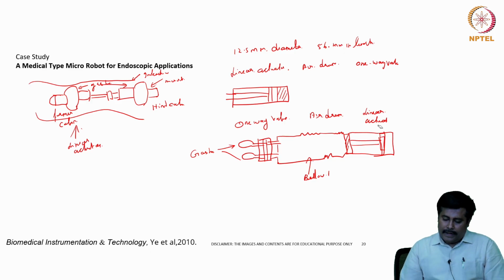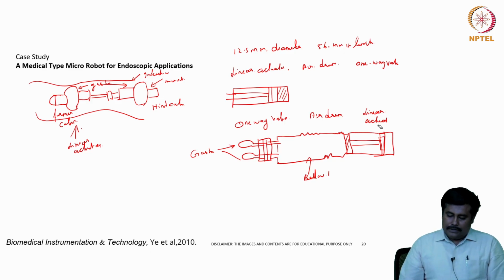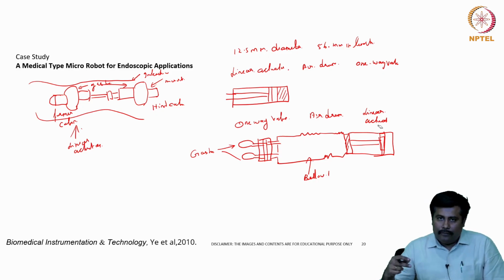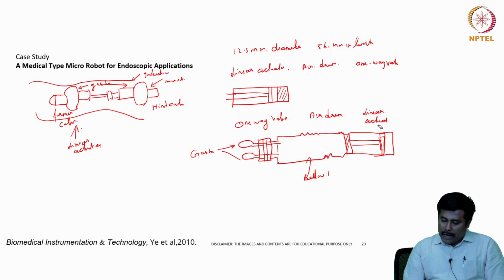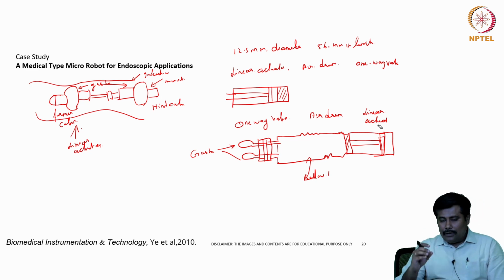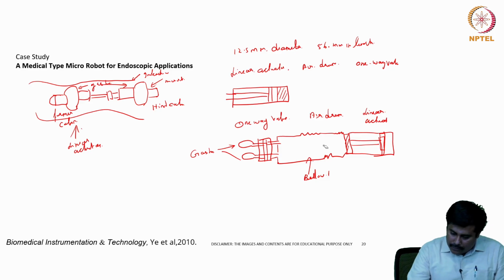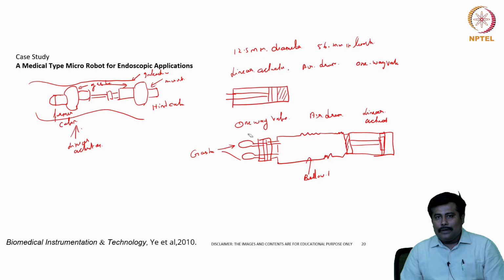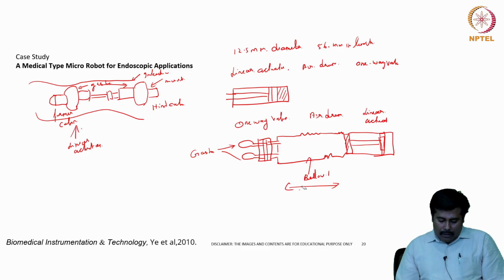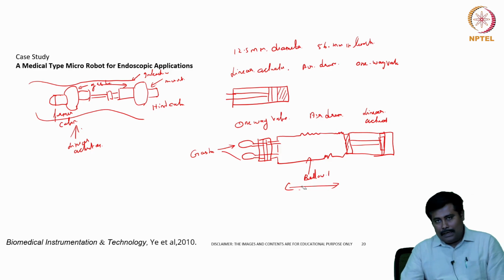So, this is a kind of linear actuator. What happens is the overall arrangement, if you see, the linear actuator is meant for giving a kind of motion to the air drum, and this air drum will give a kind of inchworm mechanism. The overall locomotion happens through this air drum, so we are trying to actuate this gas bag. When these gas bags get actuated, appropriately we can have a kind of peristaltic motion in this particular air drum, and then the overall peristaltic motion is controlled by this linear actuator.